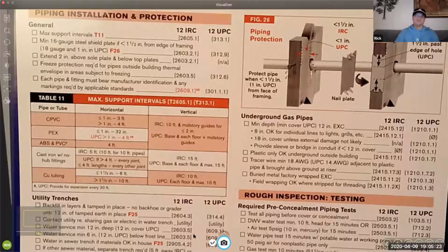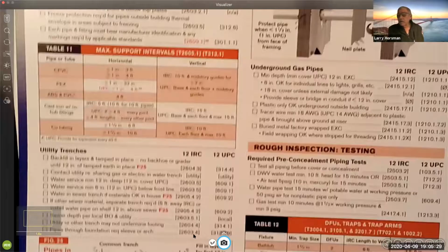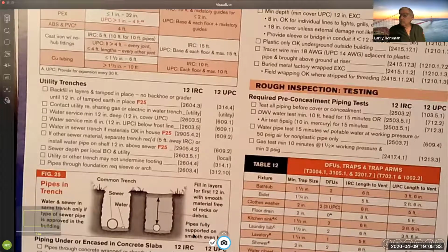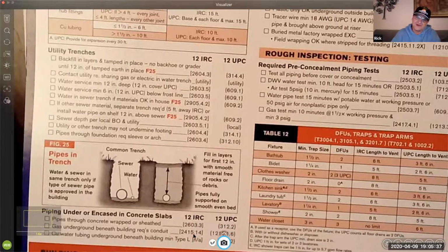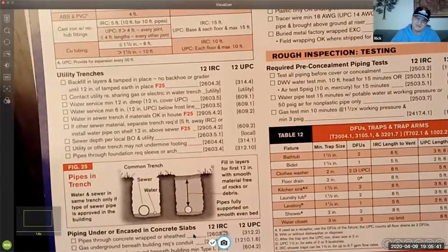Water hammer devices are for that too. Yeah, Watts makes those little water hammer devices. That's why I like the screw-in angle stops on older houses that have too high a pressure. Those little quarter turns have a tendency to slam the water. Right.